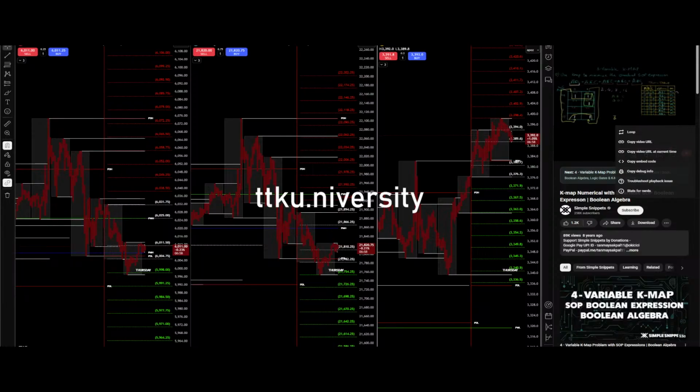Now for the second group, we write the values separately. We have 0 0 1, we have 0 1 1. As you can see here, we have 2 variables A and C whose value does not change in these 2 records, and B changes, that is B is 0 in the first record and B is 1 in the second record. So we exclude that, we take an OR and we write down these common terms, and since A is 0, we need to take a complement. This is a SOP, and guess what guys, this is our final answer. That is, if we simplify